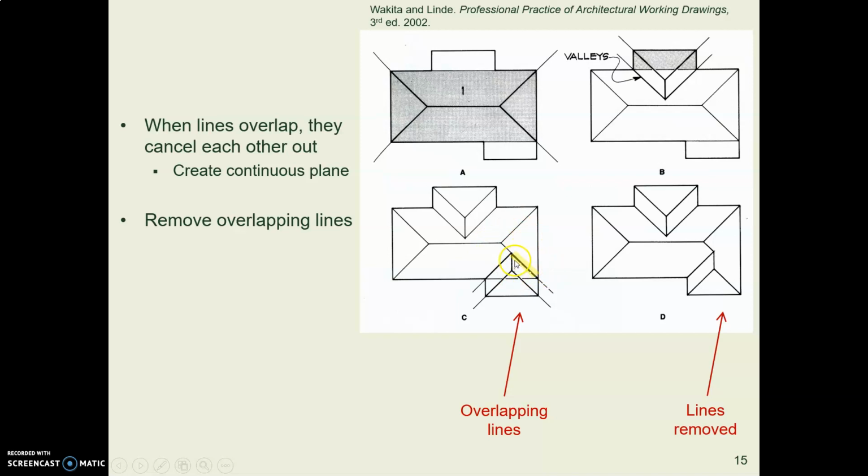So where we see these two lines overlapping each other, that's our clue that we should get out our erase command and just erase the whole thing from inside there. Get that out of there, and you are left with this nice flat surface here with those lines erased.